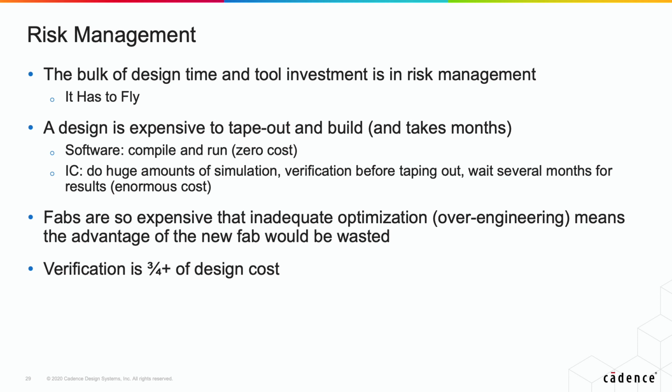And unlike software, where you can compile it and run it and see whether it works or not, the equivalent is to tape out the chip and build it. That takes multi-millions of dollars just to build a chip, even if you only want one, which is known as a prototype. And it takes literally months to get the prototype back. So that's not the way you decide whether your design is good or not.